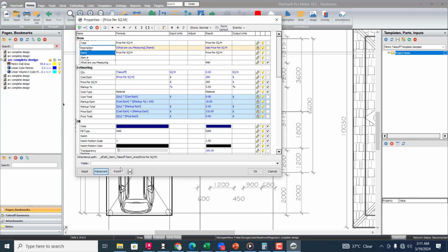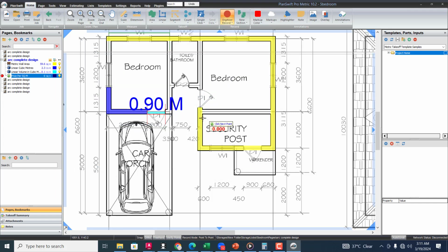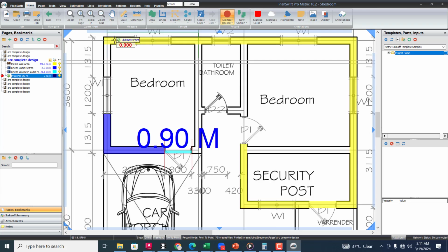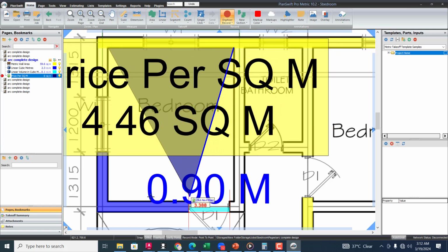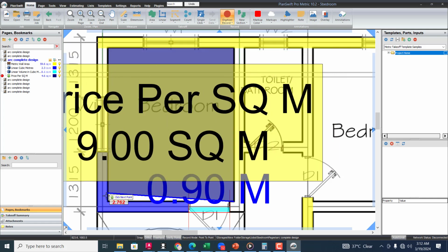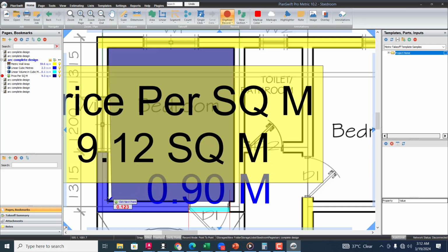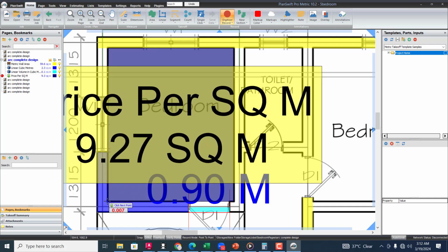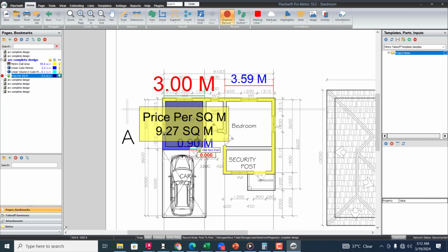So here I will just click on OK. I'm leaving every piece of information just as it is. Now to do this takeoff proper, I can just go around this. Now if I click this, and I bring this here, and don't forget, if I want to end it here, I will double click. Once I double click, you can see that part has been taken off.